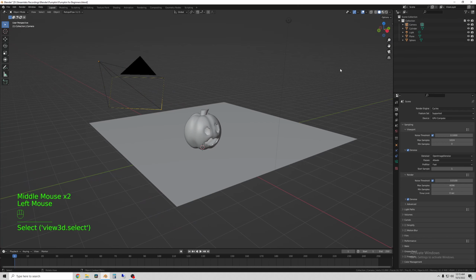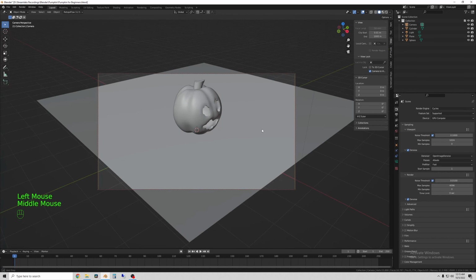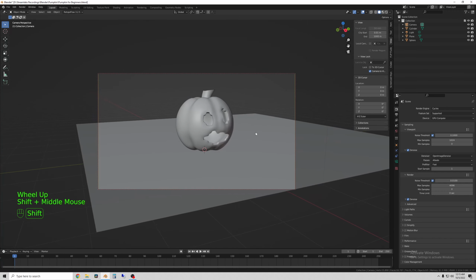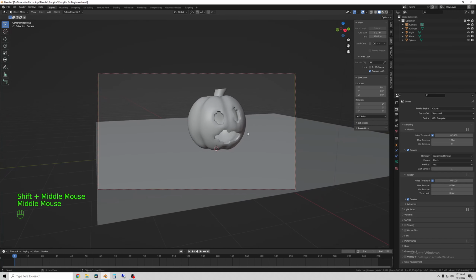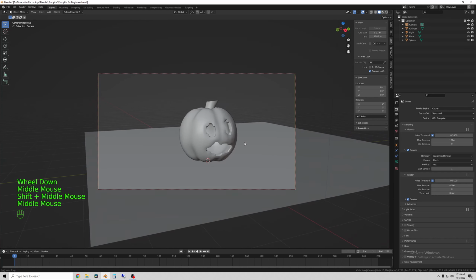So what we're going to do is come find this little arrow by the 3D gizmo here. Either click on this or you can hit N on the keyboard. That'll toggle this on and off. And then go to the View tab here, and click on Camera to View. So now when we click into the camera view, we'll get this screen, but whatever way we move, the camera comes with. So now we can get our scene set up and we kind of know where our camera is supposed to be. So we know what parts of it to modify.